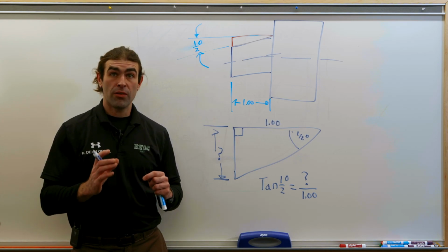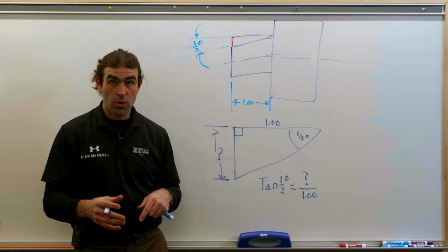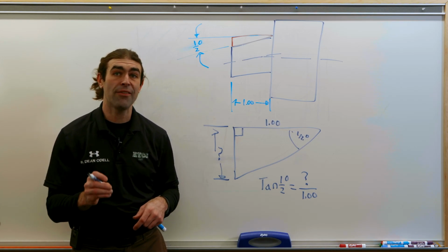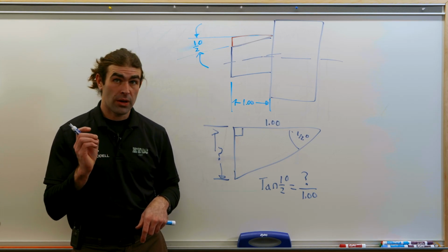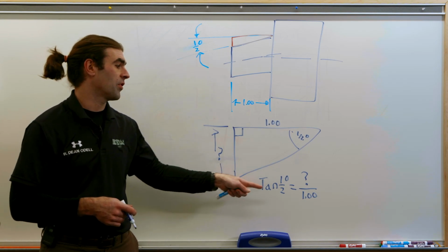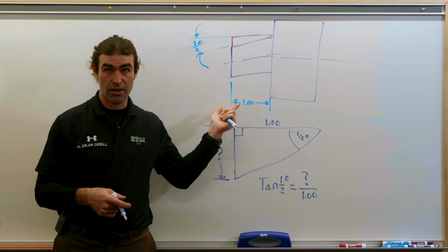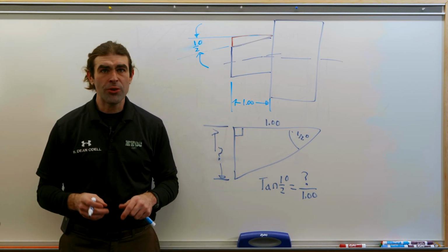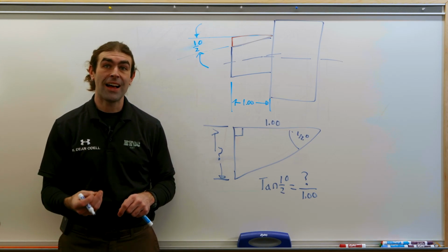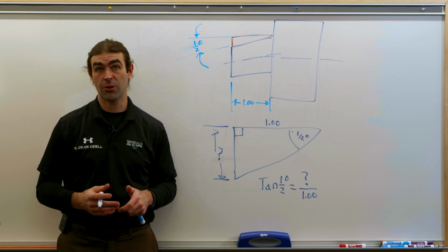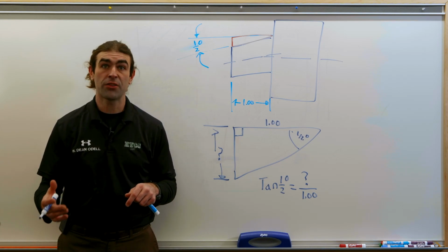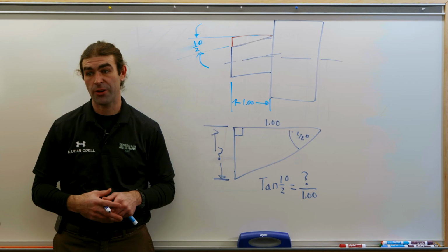So this is an example of why rule number 1 matters. It only applies to individual features, not multiple features. We have to use GD&T to make these parts fit together. Now, we could also say, okay, well, why don't I just take 8 thousandths off of the diameter of one of these? That would work as well. But what I'm trying to get across here is that if you let dimensions go to the title block tolerances, you can have unintended consequences. So it's good to use GD&T so you don't have to deal with this and do all this extra trig to figure out if the parts will fit together, okay?